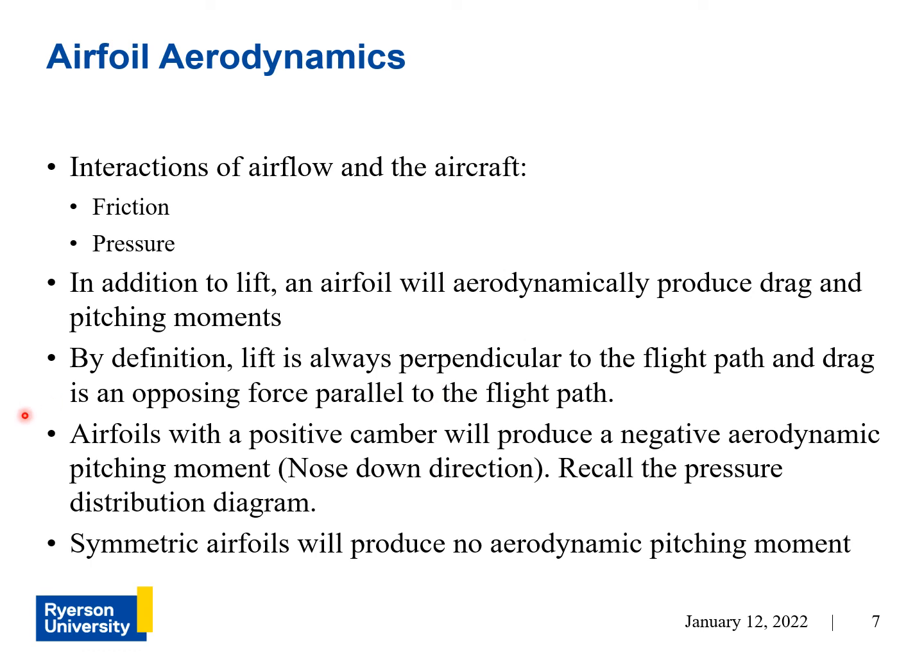And airfoils with a positive camber will produce a negative aerodynamic pitching moment, nose down direction. That again is my earlier explanation of the pitching moments due to the pressure distribution. And symmetric airfoils will produce no aerodynamic pitching moment, and that's because the upper surface of the wing and the lower surface of the wing will have the same pressure distribution, and the way that the pressure is distributed on the surface is going to cancel them out.